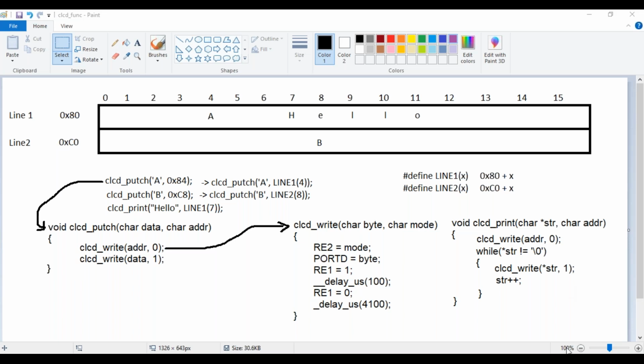Now, as we have the null character, there is no need to give an end address for the microcontroller. It stops when it sees null. I'm not even giving the next addresses. I'm giving only the first address, that is 0x87. After that, I keep giving only the characters one after the other. In that case, the address will be updated automatically by itself.